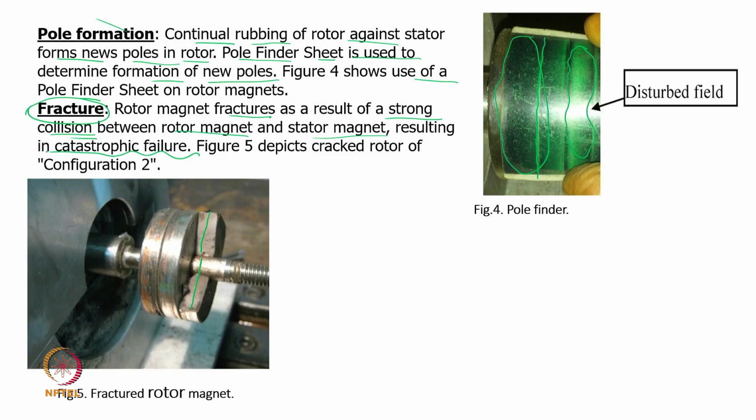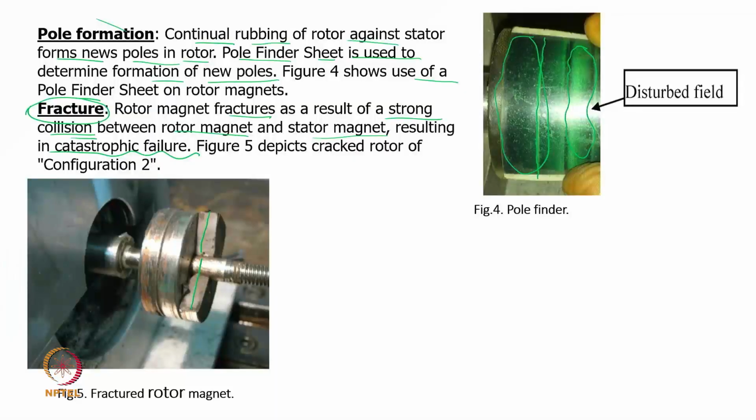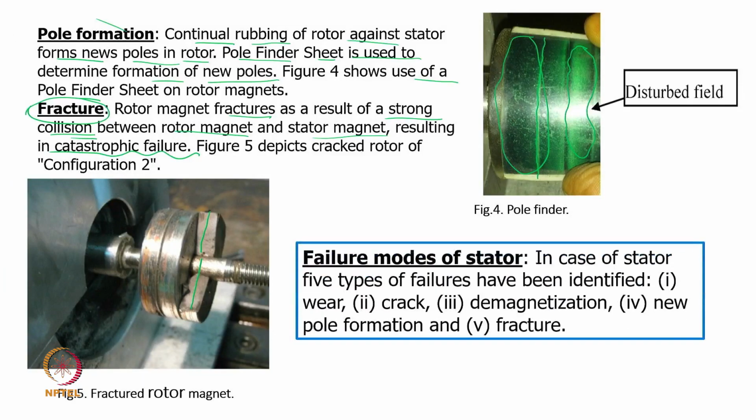So, in this case particularly FMEA was really appropriate to utilize and come up with how we go ahead with the solutions. Now, this was rotor related. Next one is the stator, the second component, and we also found similar failures because there is also a permanent magnet and relative speed and some sort of loading.